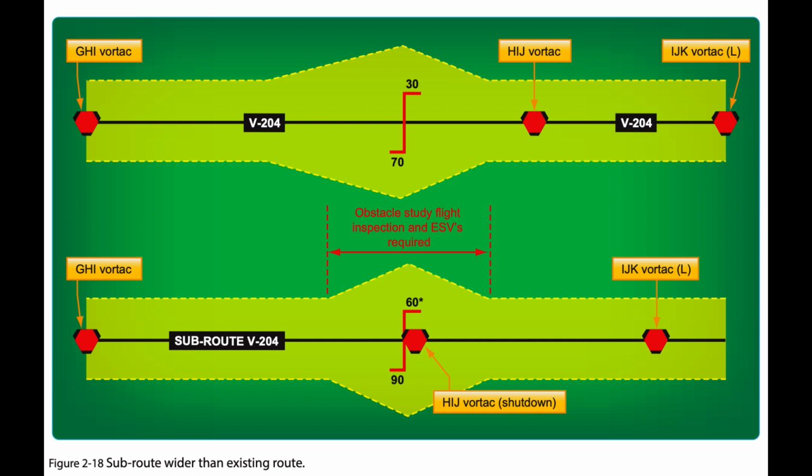A minimum en route altitude, MEA, and a maximum authorized altitude, MAA, are provided for each route segment. Temporary reporting points may be substituted for the out-of-service facility and only those other reporting points that are essential for ATC. Normally, temporary reporting points over intersections are not necessary where center radar coverage exists. A minimum reception altitude, MRA, is established for each temporary reporting point.